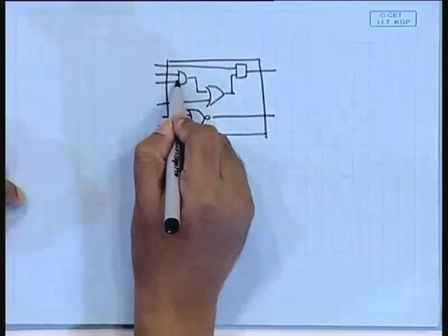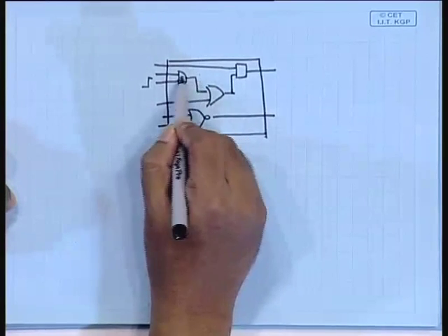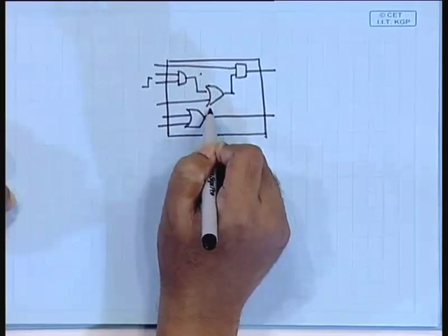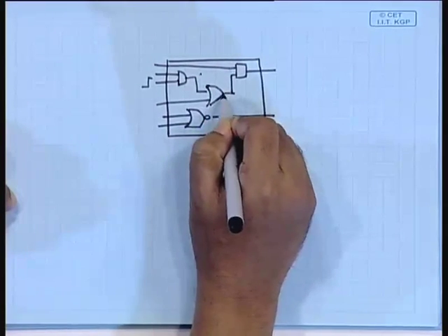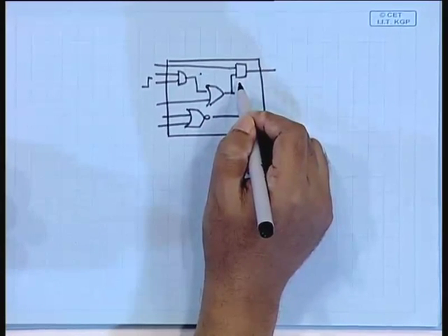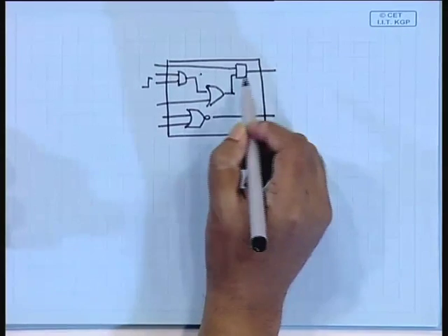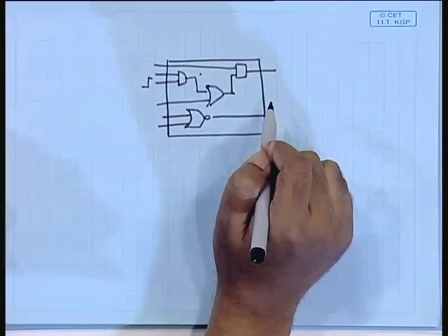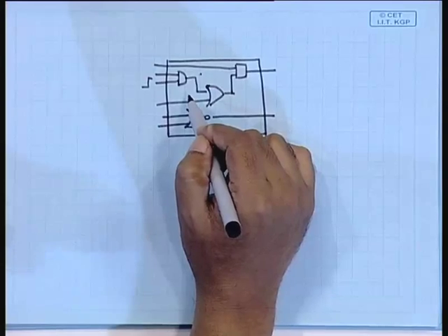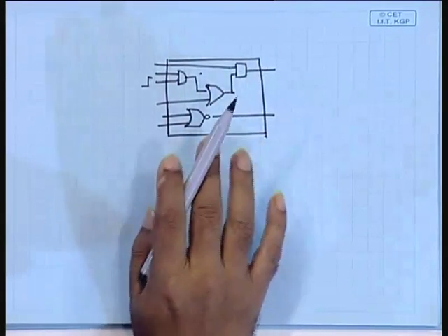Suppose there is an input change in one of the gates, then we just propagate it along the output of that gate and see what are the fan outs of that gate, and then again take those gates, schedule events on them, and we continue in this way until the circuit reaches a steady state. Now, the good thing about this is that even if the circuit has a combinational loop, you can still keep on scheduling the events until the circuit stabilizes.